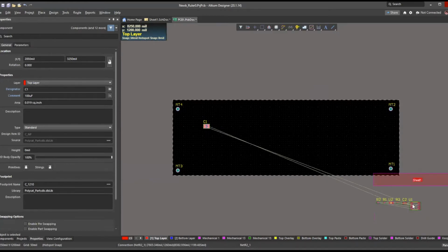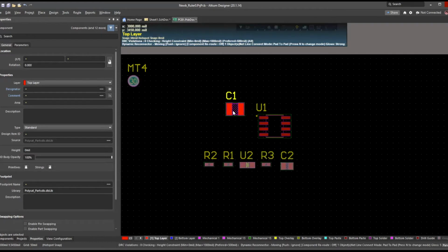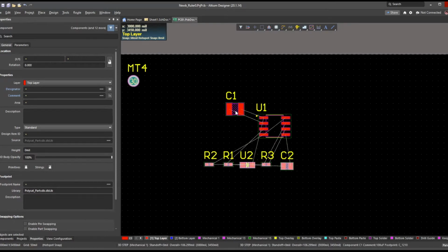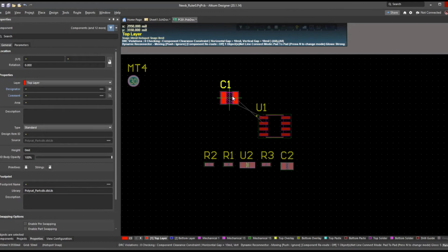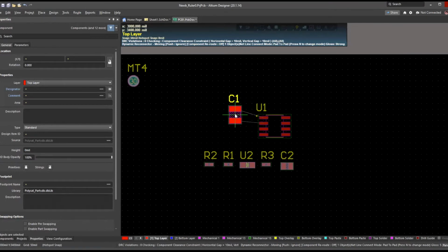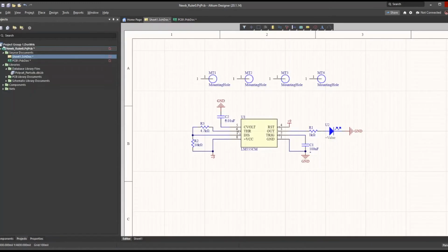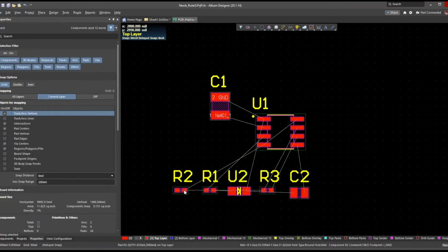You can actually just select all of them, drag them onto here. These lines define the connections between all the components. So you can see here, it's kind of nice. I can drag it, press spacebar to rotate it. Here, it's kind of tangled, so I'm just going to untangle, press spacebar. Yeah, looks clean. So you can look back at your schematic if you want to remember where your components are, and typically, of course, when you lay out a schematic, you want to lay it out approximately how it'll look on the PCB. So I'm just going to do just that.